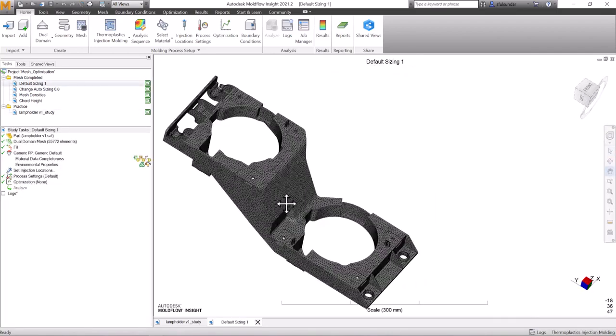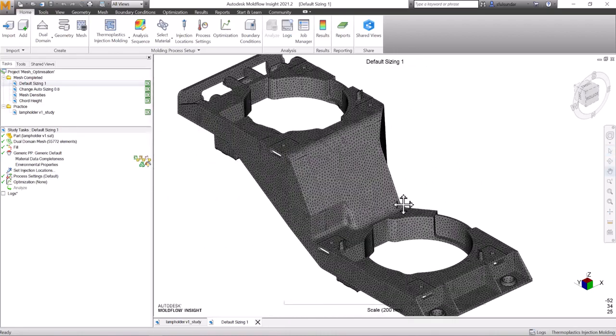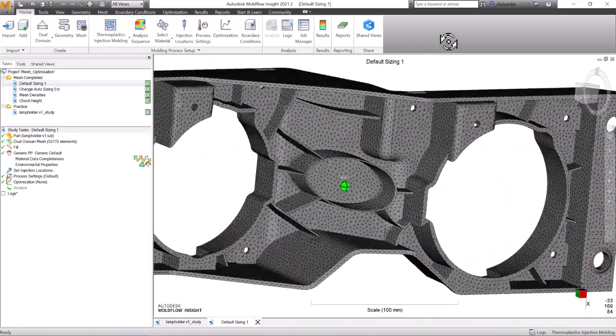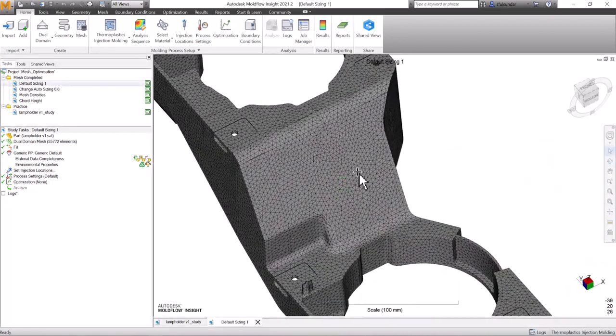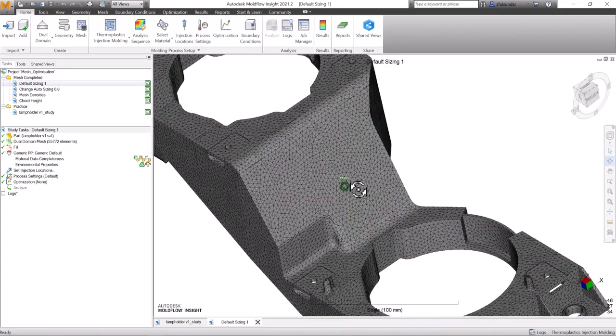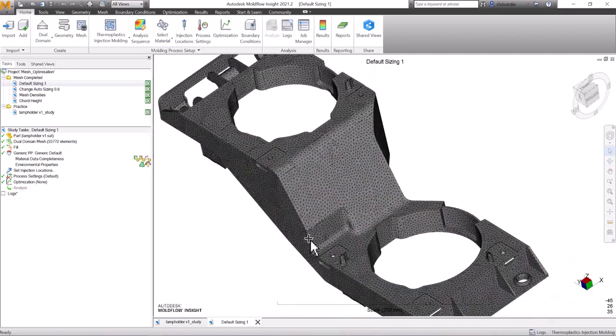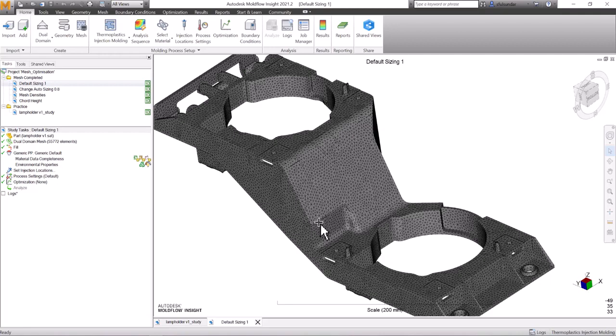Pretty much it has created a nice mesh, and of course the feature that is on the back side is also getting imprinted over here. So I'm going to get a sink mark, or the impression of the sink mark, nicely if you have this mesh match ratio, or the matching of the elements of the feature on the other side.